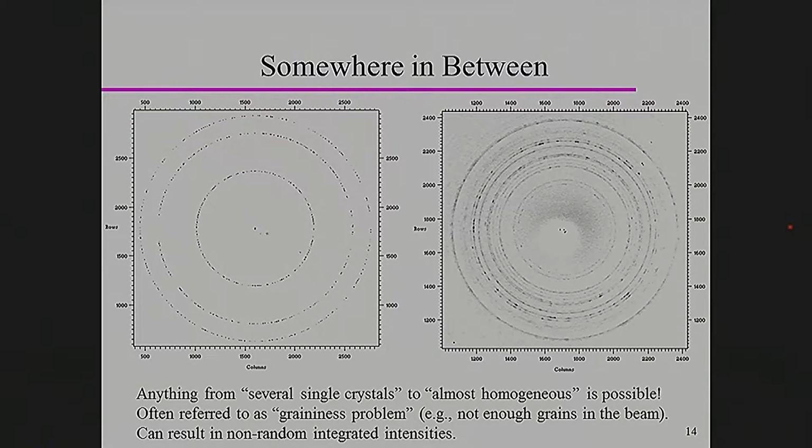Okay, now this is actually data that we collected during a powder high pressure experiment. Okay, and you saw the setup in Christine's talk where you have that little diamond, that little gasket. We are just by the setup limited with respect to how much powder we can put in there. And so unless the powder is extremely well ground and really in that 1 to 2 micron range, you will likely see something like that. Okay, that is usually when my grad students really learn what grinding a powder means. Okay, I usually let them pack 1 cell just for the fun of it when they say they've ground it enough, and most of the time they haven't. So if your advisor tells you grind something well, do it. Surprise them.